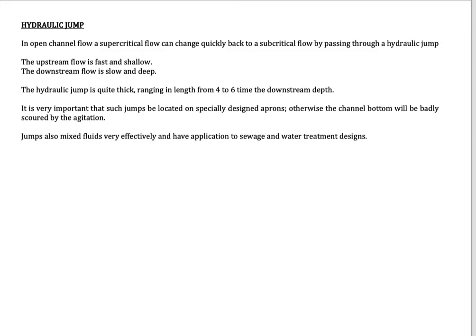The hydraulic jump is quite thick, ranging in length from 4 to 6 times the downstream depth. It is very important that such a jump be located on specifically designed aprons. Otherwise, the channel bottom will be badly scoured by the agitation. Jumps also mix fluid very effectively and have application to sewage and water treatment design.